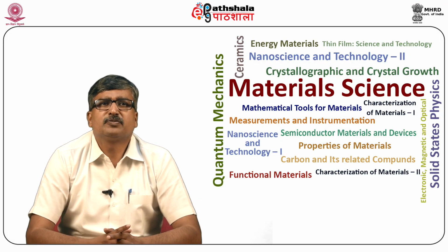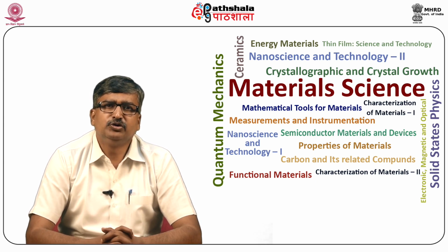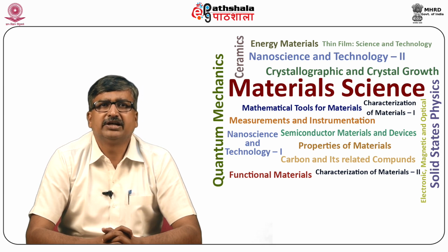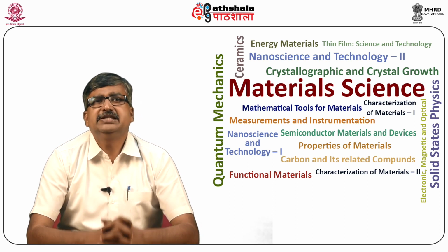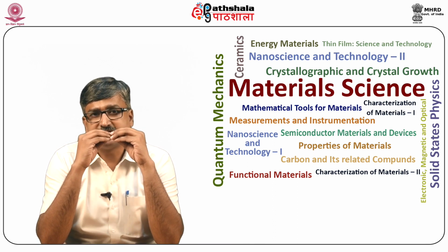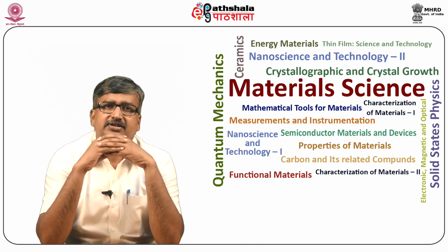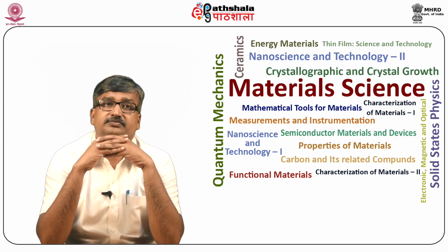Let us discuss the processing parameters. Dear student, here I will introduce you to the different processing parameters which are required to be adjusted during electrospinning. The first one is the voltage. Within the electrospinning process, applied voltage is the crucial factor. Only when the applied voltage is higher than the threshold voltage can the charged jet ejected from the Taylor cone occur.